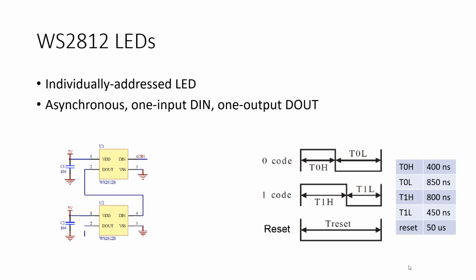So at some point, once you take the frame time and you back out the reset time, you only have a certain amount of time left over where you can program the LEDs. And the programming time for all the LEDs is a function of how many LEDs there are, because they're programmed one at a time, right? I mentioned in the lab sheet that, given these parameters, you're limited to basically a 300 by 200 array of LEDs or so, assuming you're trying to update them at 30 frames per second. Of course, you can update them slower, but if you're playing a video, generally you're at 30 FPS, right? Okay, so that's how those work.